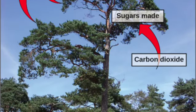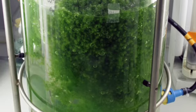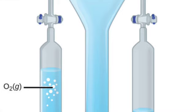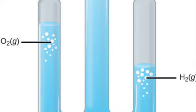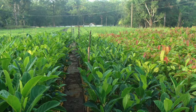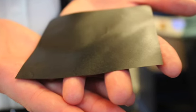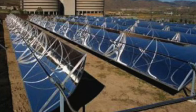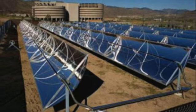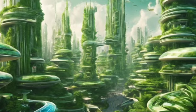Process overview. High temperature and high pressure conditions. HTL involves subjecting organic feedstock to elevated temperatures, typically between 250 degrees Celsius and 550 degrees Celsius, and high pressures, typically between 10 and 25 MPa, in the presence of water. Liquefaction of biomass. The combination of high temperature and pressure facilitates the liquefaction of the organic feedstock, breaking down complex organic molecules into a liquid bio-oil.